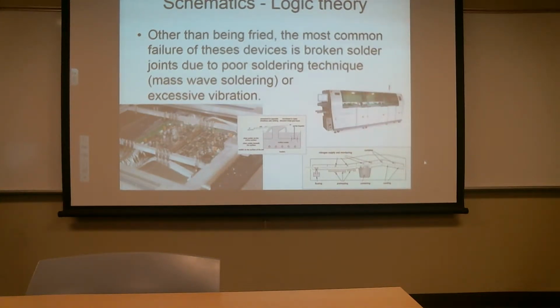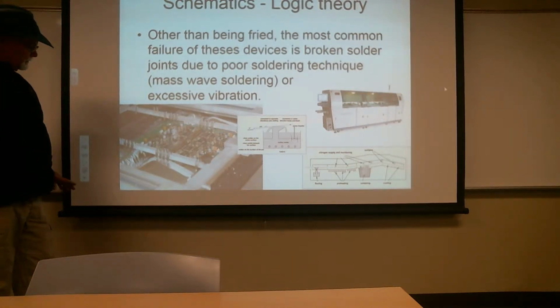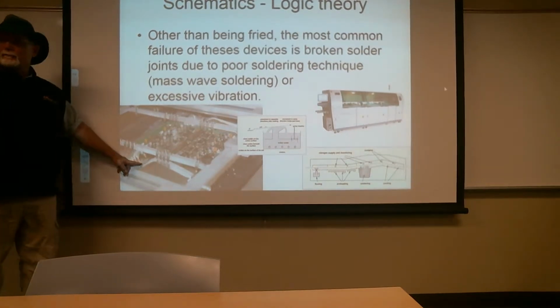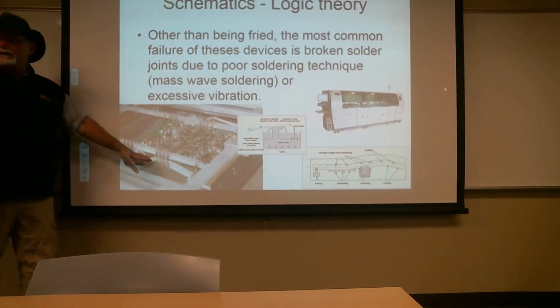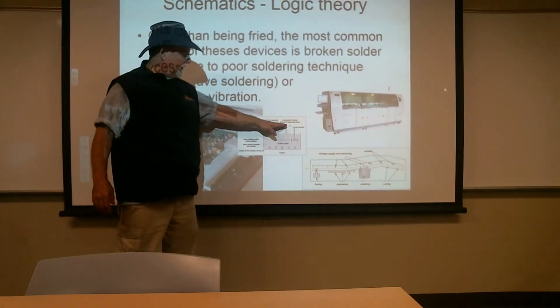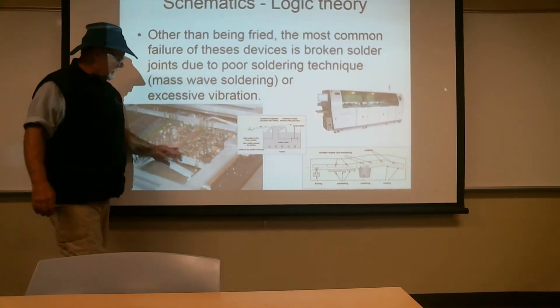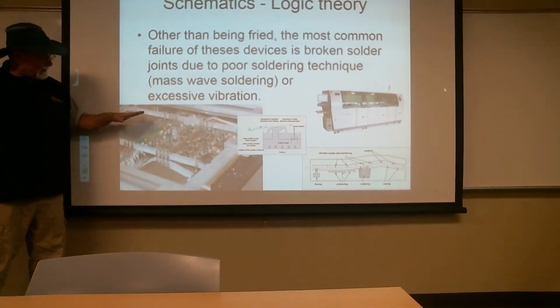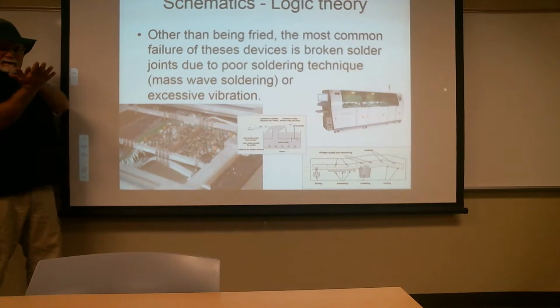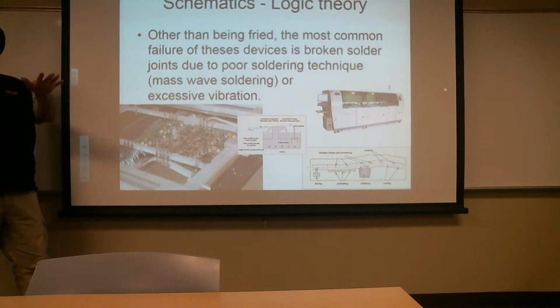In this one, I just showed you a couple of pictures of the device that actually does wave soldering for a lot of your surface mount technology. This is actually through mount technology. What they do, this sort of silvery area here, that all silver, that's molten solder. It's molten solder that's flowing up in here in a wave that comes out. And that wave is very carefully controlled. And so the solder boards move along a platform, and they just sweep right across that wave of solder sitting there, dip into it just enough to solder everything.